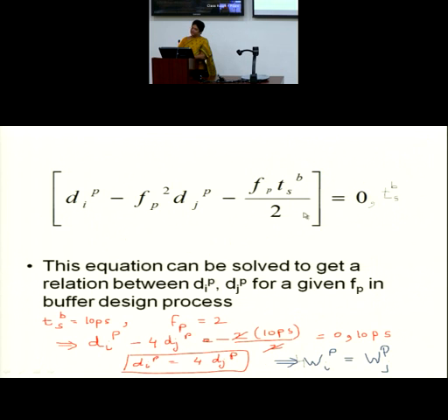So now you can use this equation to arrive at what W you should have for each device, which minimizes your delay or the skew variation, or keeps the delay within bound so that the skew remains within bound.